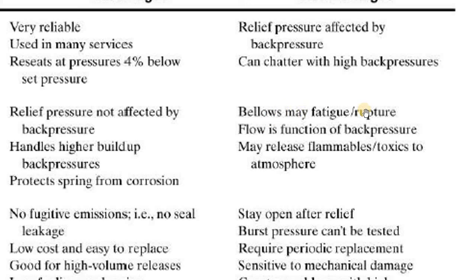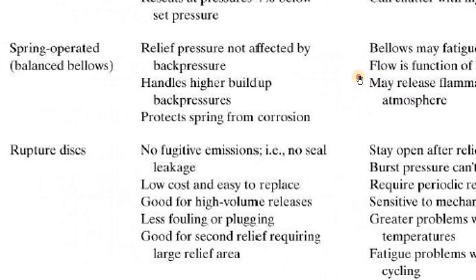This bellows, over time, gets fatigue because it goes up and down and up and down, and it ruptures. Flow is a function of backup pressure, that's for anything there. May release flammable toxics to the atmosphere. I forgot this, I didn't have that in mind actually, but this is something that could happen.